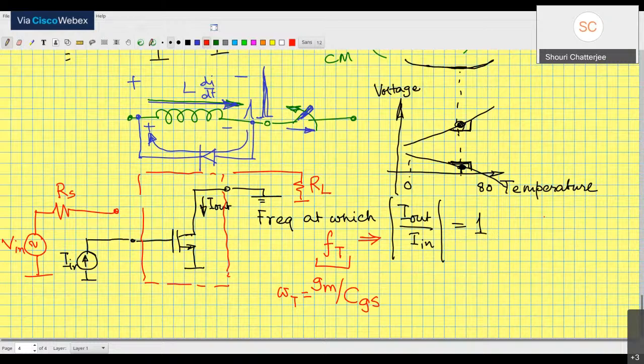All right. So power supply rejection ratio is defined as the gain that you see from the input. So think of your circuit as a 3-port network. So far we have been talking 2-port, right? At port 1, I have the input. At port 2, I might have some noise coming in from the power supply. Maybe some ripple or some noise, all right? And I have the output.